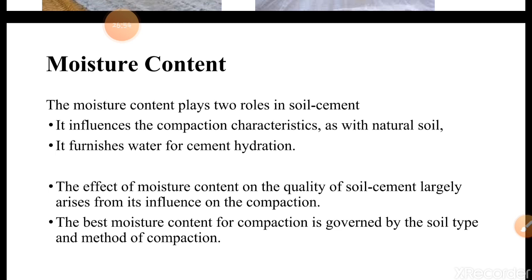For coarse grained soils, we roll either using vibrations or smooth wheel rollers. Similarly, for fine grained or clay soils, we require sheep foot rollers or pressing. If we adopt the proper methods, we can definitely get the required strength of the soils.